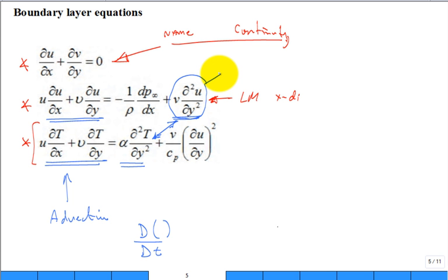And so it's diffusion of linear momentum through the viscosity. The faster fluid on top of the slower fluid is going to want to speed up the slower fluid. And conversely, the slower fluid is going to want to slow down the faster fluid above it. Okay. So there's a transfer of something. Linear momentum.